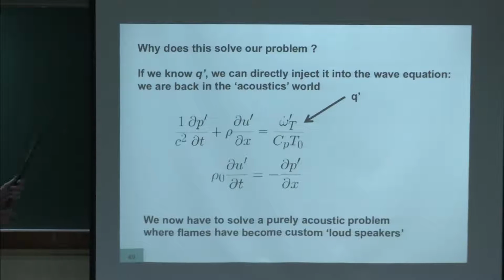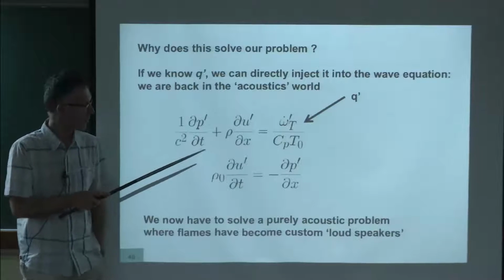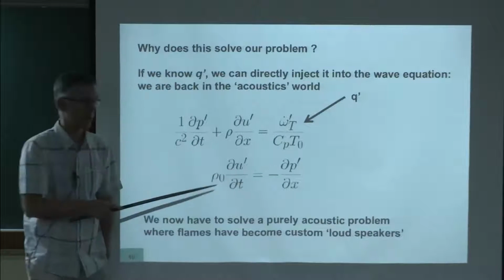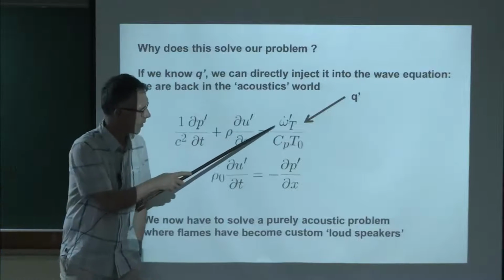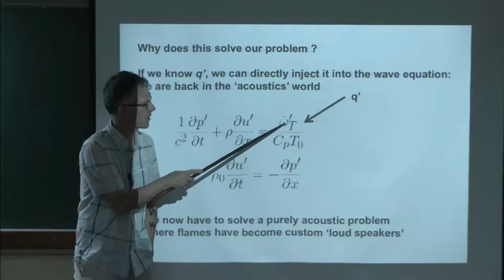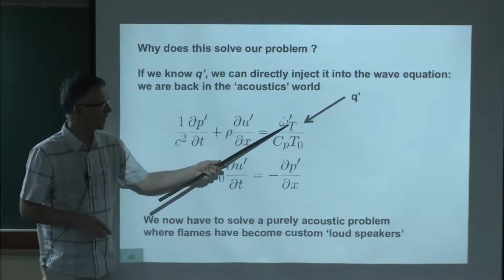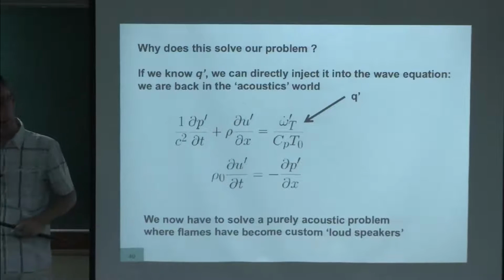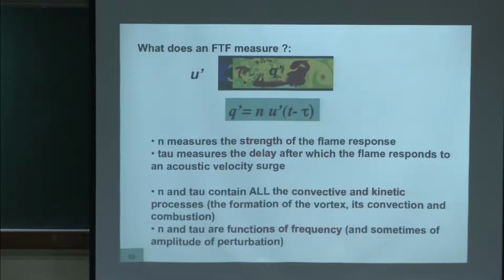So why is it so? These are the equations I wrote before for the acoustics with combustion, and remember, that's the normal equation without flame, or with flame it is the same. And here, the only additional term in this equation is the unsteady heat release. So if I know the unsteady heat release here, I can completely close the acoustic equations and find a much simpler solution to my problem.